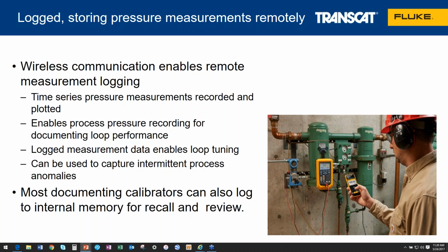Most documenting calibrators can also log to internal memory for recall and review, but again, the remote logging can be a good tool for capturing intermittent process anomalies.